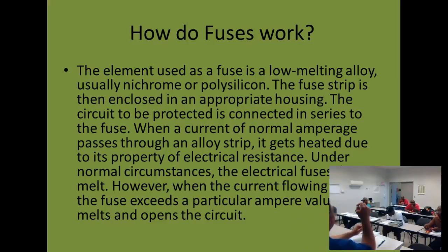And so a lot of times we'd be working in dark places, and we were just ohming out, and as you ohm stuff out, if you could hear it go beep, you knew what you had, because you couldn't see, you couldn't read it. Okay? Very few people use continuity anymore, okay? But it's still on there, it's kind of a holdover from the old timers. So continuity doesn't mean zero resistance. It just means there is a path, okay?